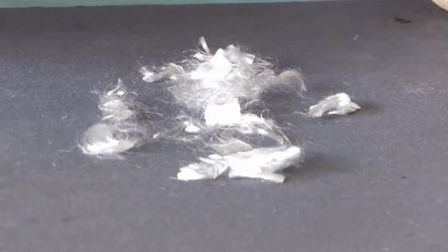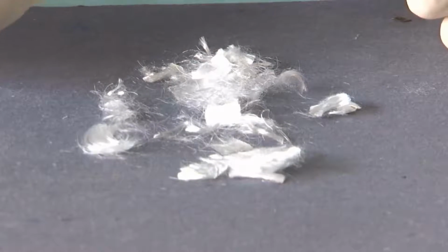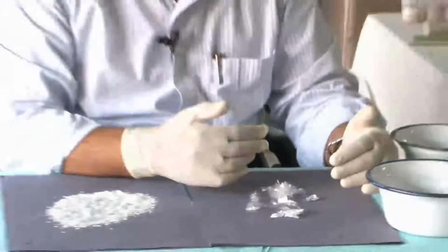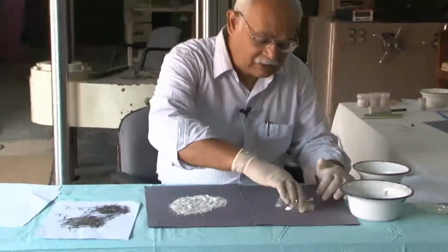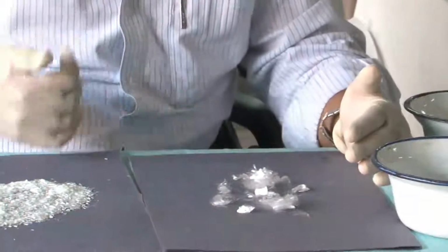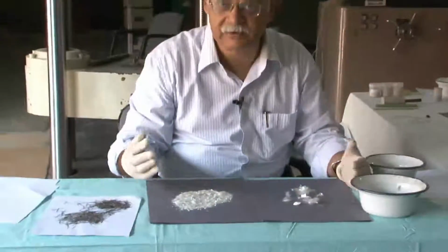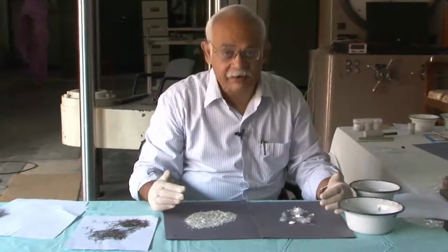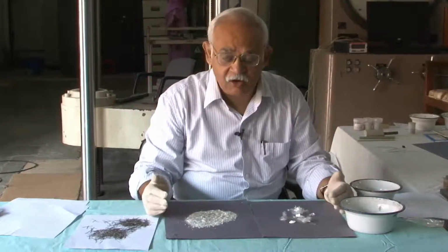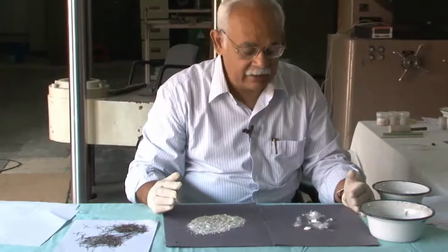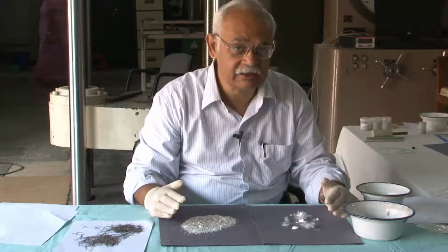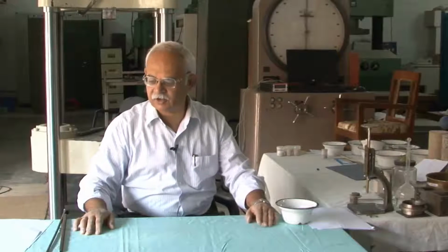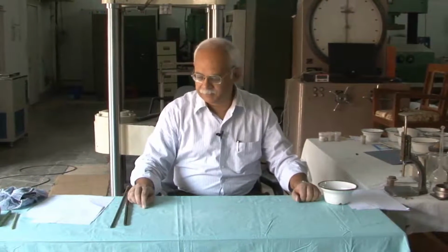We will study the properties of steel fiber or glass fiber reinforced concrete subsequently, but please remember that all these fibers, whether they are polypropylene or glass or steel, different shapes, different sizes, different diameters, different lengths, all need to be mixed in concrete, and therefore, we have to ensure that their distribution throughout the matrix is homogeneous. Any discussion on concrete construction is not complete unless we talk about the reinforcing material as well.